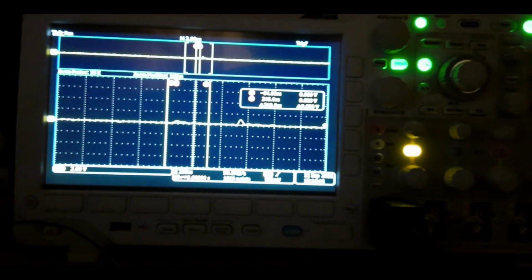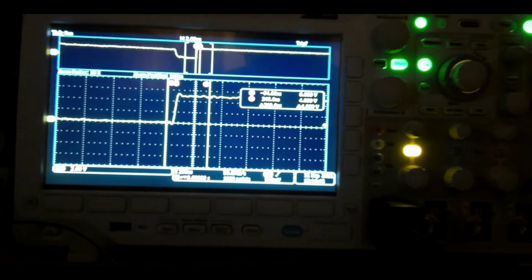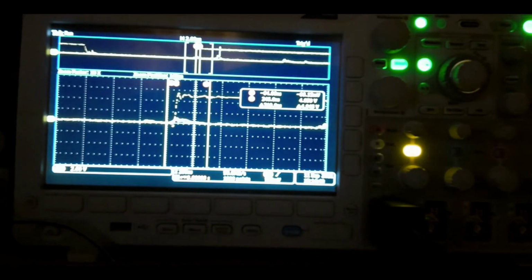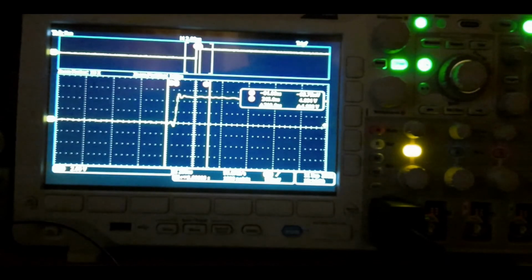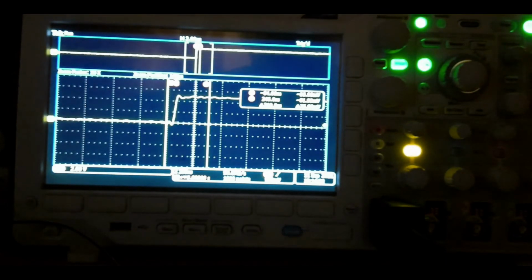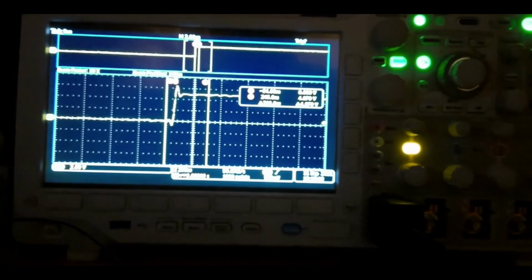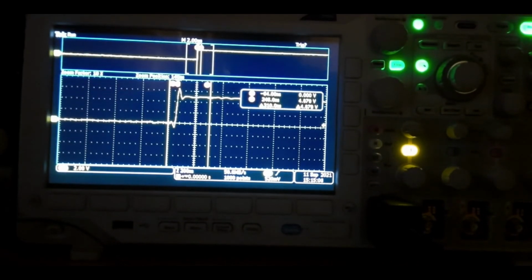So the maximum time taken by the switch to settle, you have to note that, and that delay you have to introduce in your program to overcome the issues related to key bouncing. In this way, you can measure the delay, and then correspondingly you can introduce the same delay in your code to overcome the issues related to key bouncing.